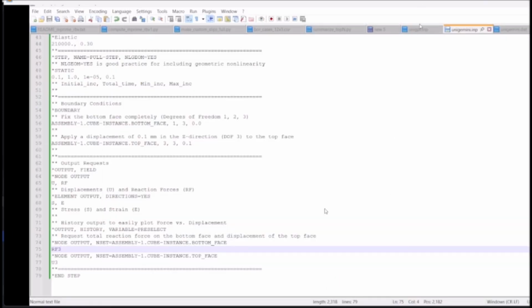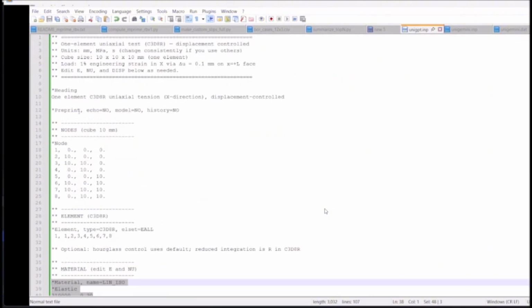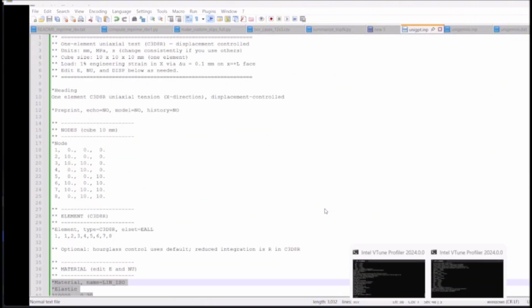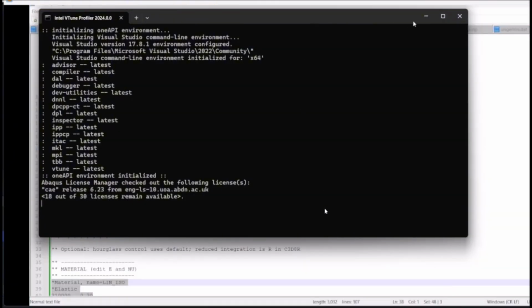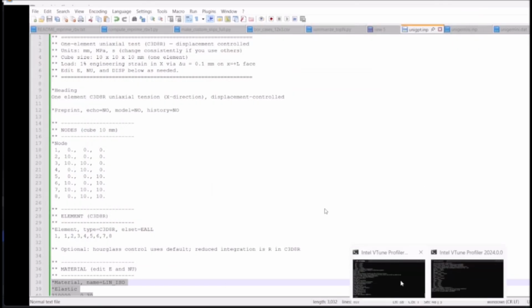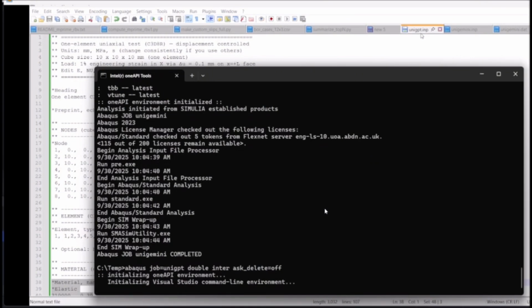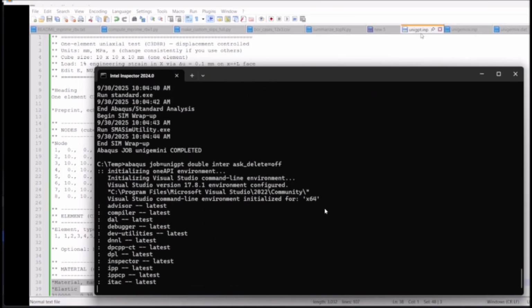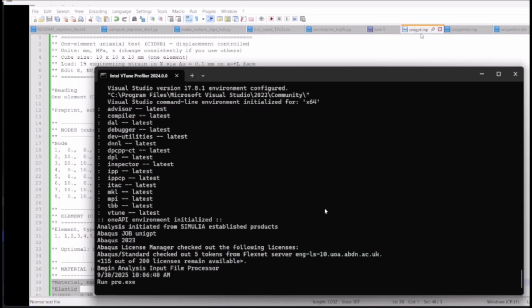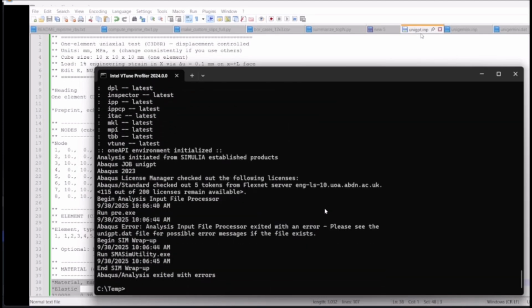Now let's move to the GPT file and run it. I already told you these line breaks will give us problems first, because ABAQUS doesn't like it when you run the jobs like that. But let me see if it works, because we are doing it in a way that we say we don't know anything about input files, right? So if somebody like me who has no idea about the file, I got the file, I copy it and run it, then let's see what sort of error I'm going to get. So you see pre-processing the file, and then there are some errors.